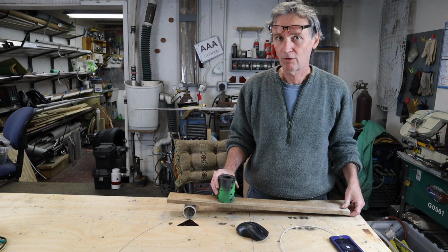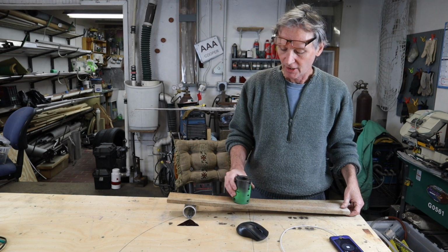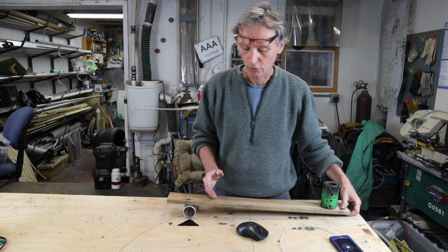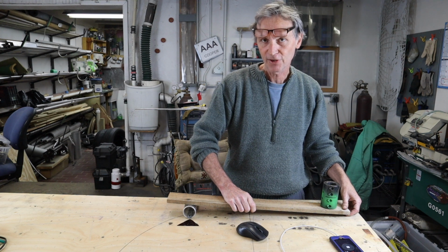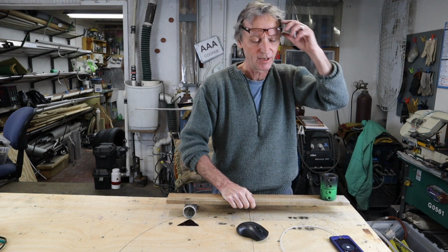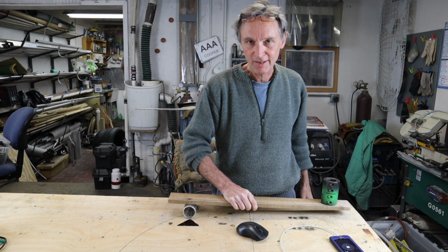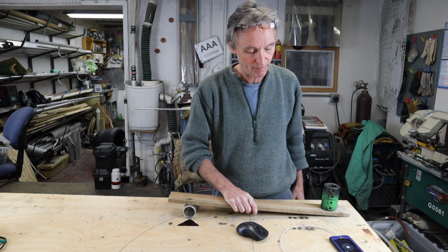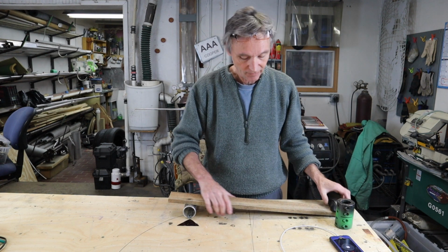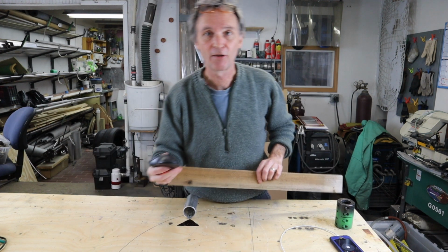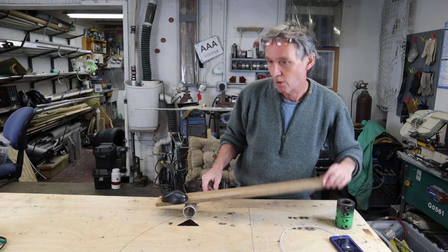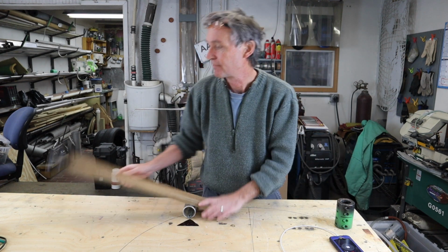Now let's scrape the barrel. Third class lever. Third class lever means both the load and the force are on one side of the fulcrum, but now the force is here. So I am lifting at some great disadvantage. Of course, this is a zero-sum game. So what we gain by that is, if we put something very light here, I can throw it very fast. Whereas I won't be able to here unless I do the same thing.